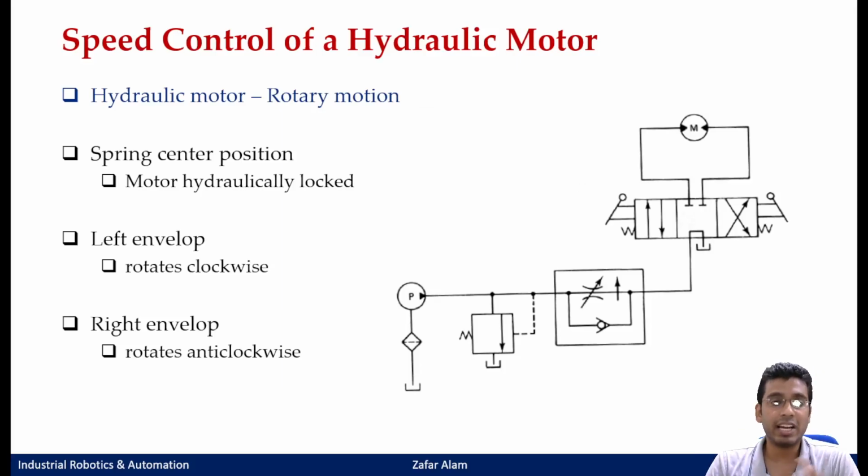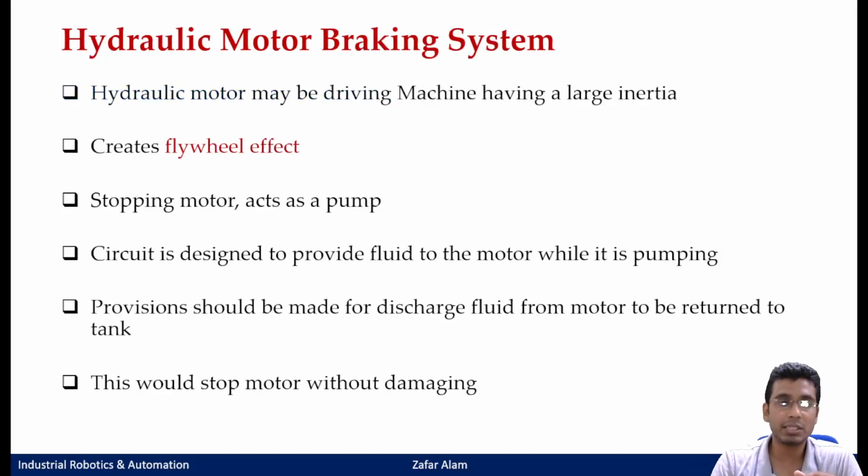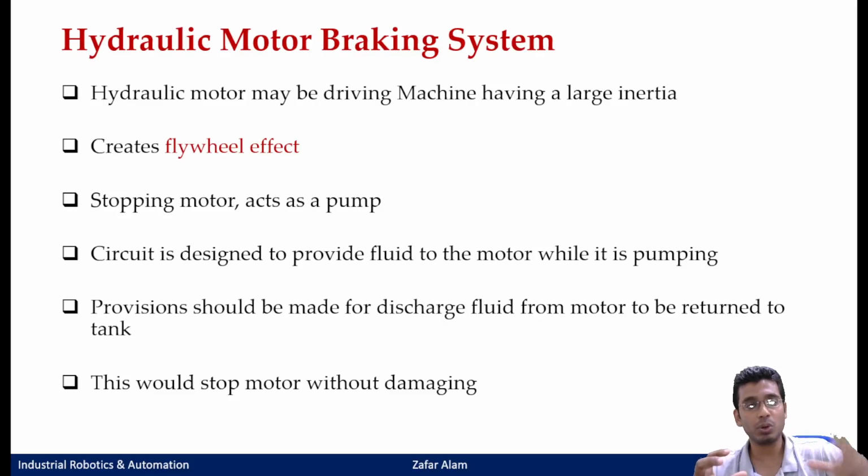Similarly, that flywheel effect: even if your power stroke is stopped, the other 3 strokes have energy getting supplied by the flywheel. A similar effect you will have when you suddenly stop the hydraulic motor by putting your valve in the center position, that is, with all the ports blocked. So suppose the 2000 kg weight was coupled to that motor. Even if you stop the flow to the motor, this load that was running would try to make the rotor run, and now your hydraulic rotor that was initially running as a motor would try to behave like a pump, right? In a pump, what does it happen?